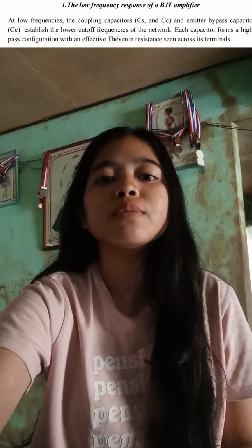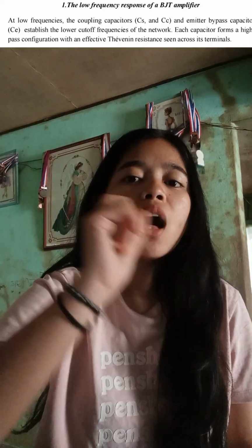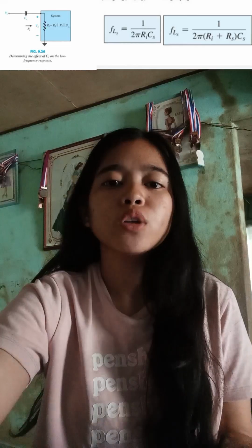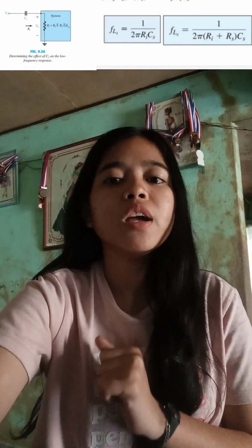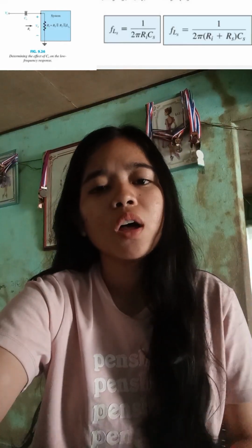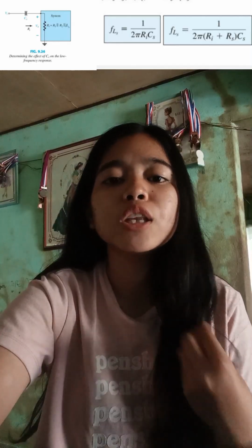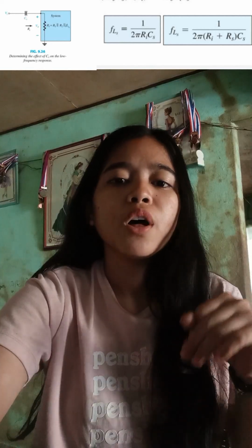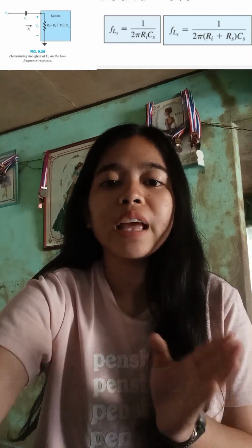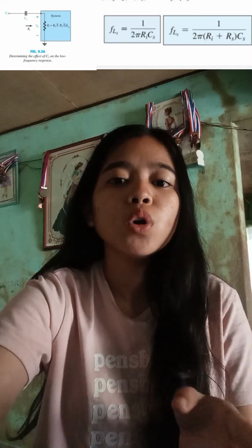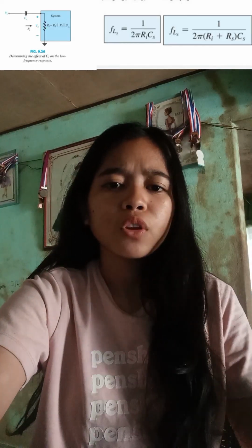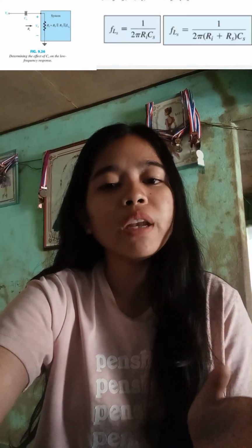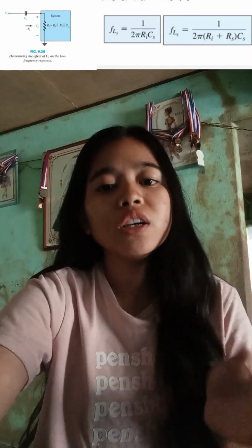So now, let us move to our first formula for the input system. We have F sub Ls is equal to 1 over 2 pi times R sub i times C sub S. As we look at this formula, it determines the cutoff frequency due to C sub S. The key here is finding the total AC resistance R sub i looking into the base. So for this voltage divider configuration, R sub i is the parallel combination of the biasing resistors R sub 1 and